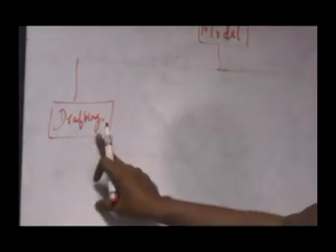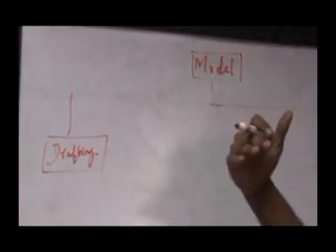Similar to the drafting packages we have seen previously, I create the model only and push it to the drafting module. There the views of the model will be created directly, with dimensions. You need not use commands to draw the views; the views are created from the model. Similarly, the same model will be pushed to another module called CAM, Computer Aided Manufacturing. We will see what that is.